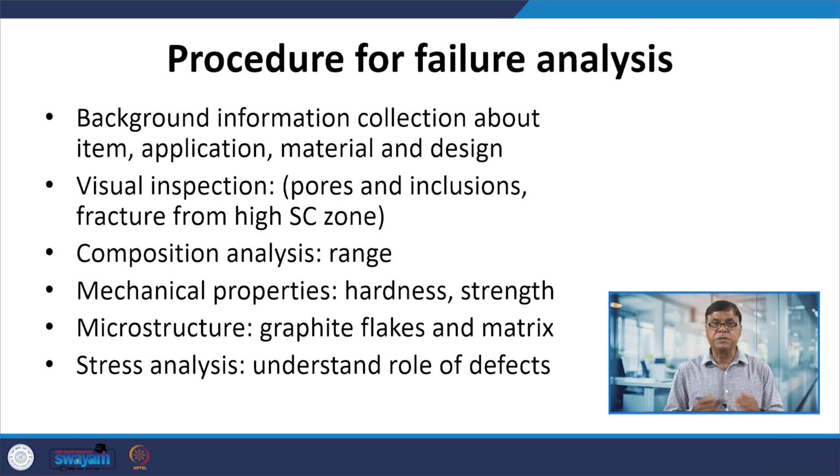So, the procedure which is normally used in failure analysis is to first understand the component itself, that is, the background information, wherein you can see what the item is, what the application was for which it was used, what the design is, what the materials are, what properties are expected, and what the manufacturing approach was, etc. This information is collected just to familiarize oneself with the product which is being investigated.